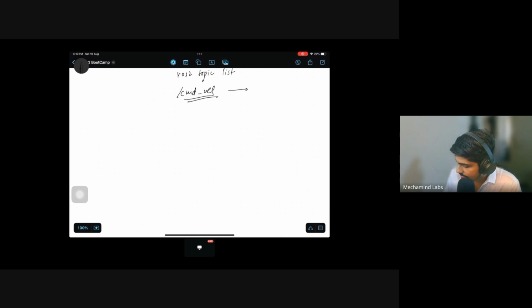So again, I did reverse engineering and found out using ros2 topic info, and here I put the command velocity topic, turtle1/cmd_vel. By this, I got the interface type as geometry_msgs and Twist message.